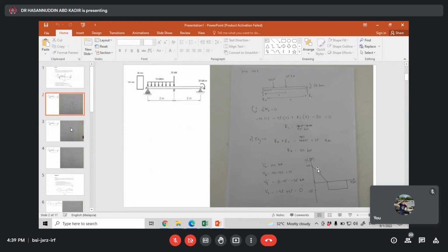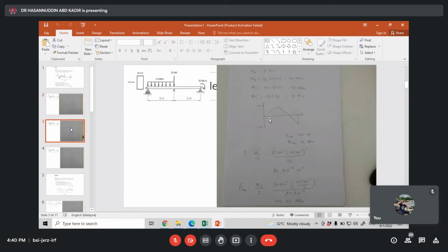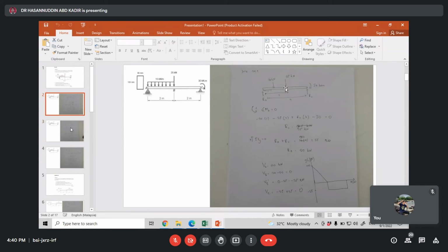Okay, bahagian sini ni untuk dia punya shear force. Ini untuk bending. So dia tak akan ada bentuk pelik-pelik lah. Distributed load sama dia hanya ada fokus concentrated load saja. Okay, cuma concentrated load tu boleh datang dalam bentuk bearing yang akan ada magnitude yang berbeza pada x-axis ataupun y-axis. Kat situ yang kita kena clear lah.